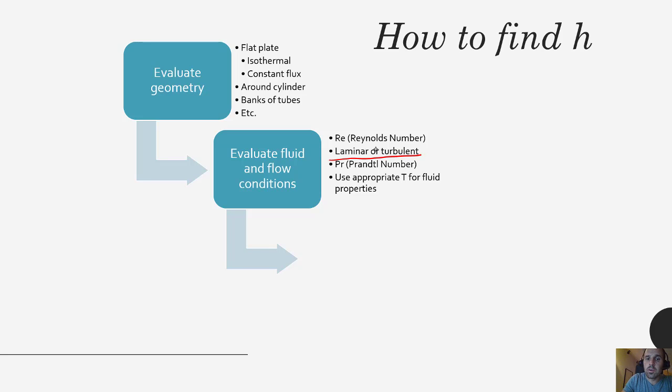And whether the flow is laminar or turbulent makes a big difference for heat transfer, so we want to determine how the fluid mechanics of the system influence the heat transfer of the system. As you can imagine, and as we've discussed, turbulent flow has a lot more circulation and a lot more mixing, so that tends to really enhance heat transfer.